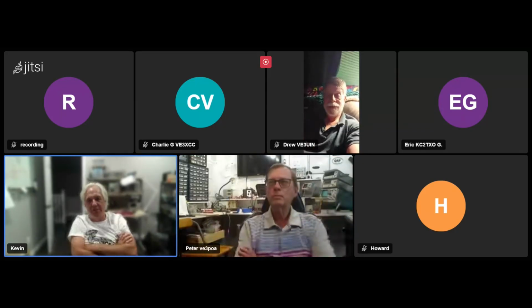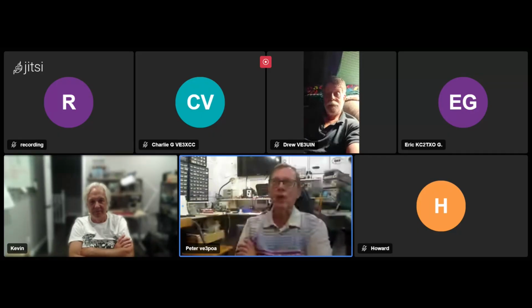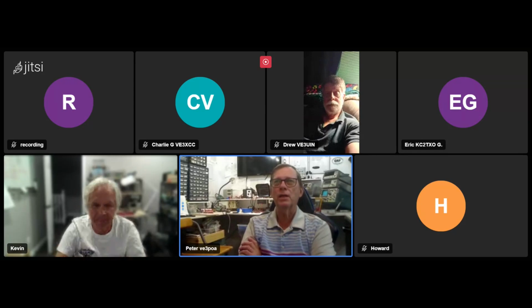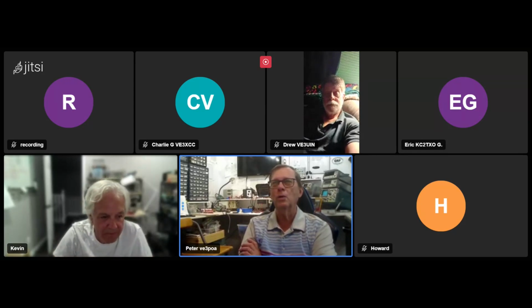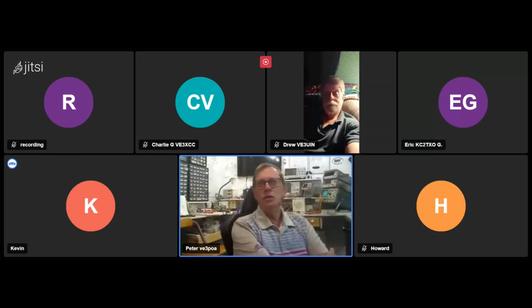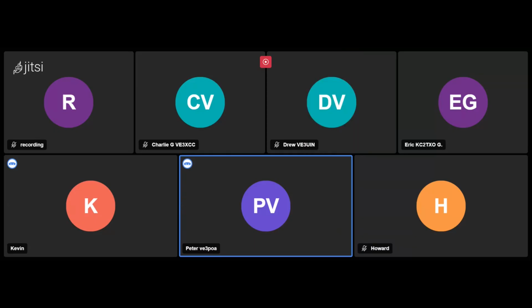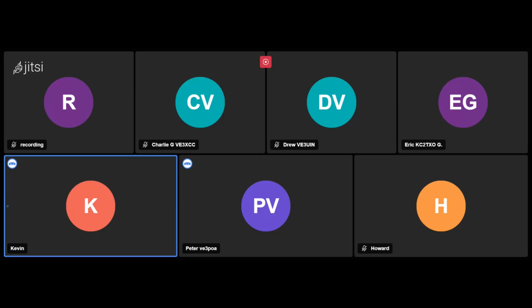Do you think you really can do a DFT in an Arduino? Because there's no floating point. Well, you know what? I've seen a project that's done it and I'm going to duplicate it. So I should know in about 3 weeks. I've designed a board for it and it's running off a nano. So we'll see. I've seen it in action. Now that's audio. I mean, you can do it with integer math too. It's just not as precise.